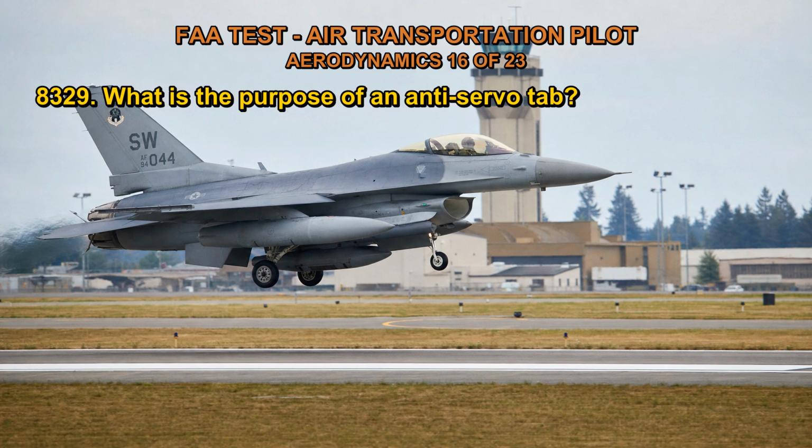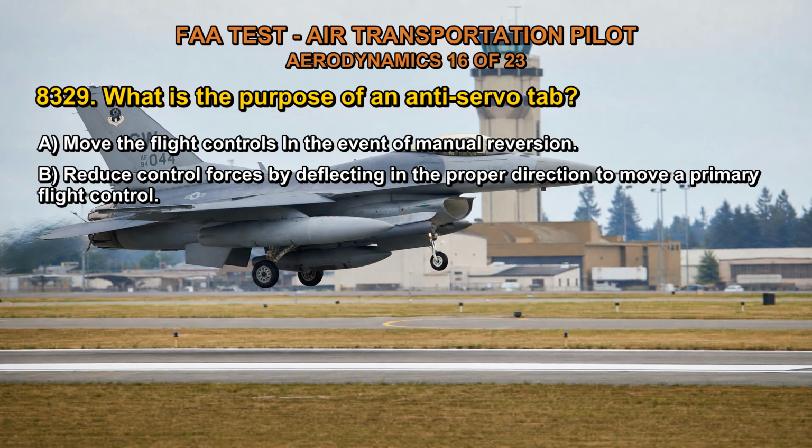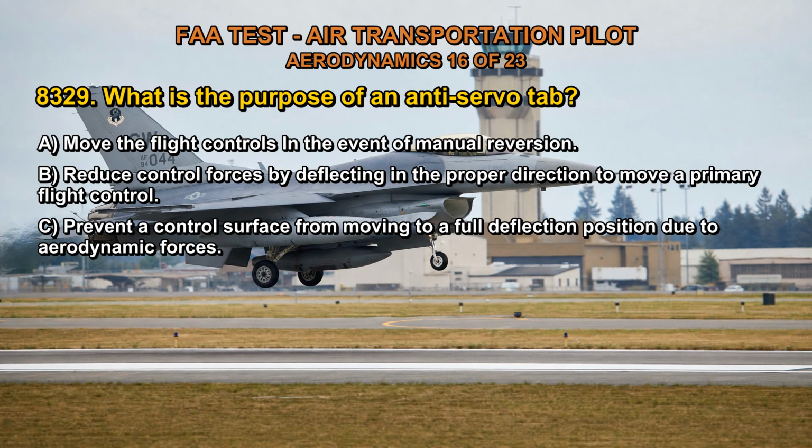Q8329. What is the purpose of an anti-servo tab? A. Move the flight controls in the event of manual reversion. B. Reduce control forces by deflecting in the proper direction to move a primary flight control. C. Prevent a control surface from moving to a full deflection position due to aerodynamic forces. The correct answer is C.